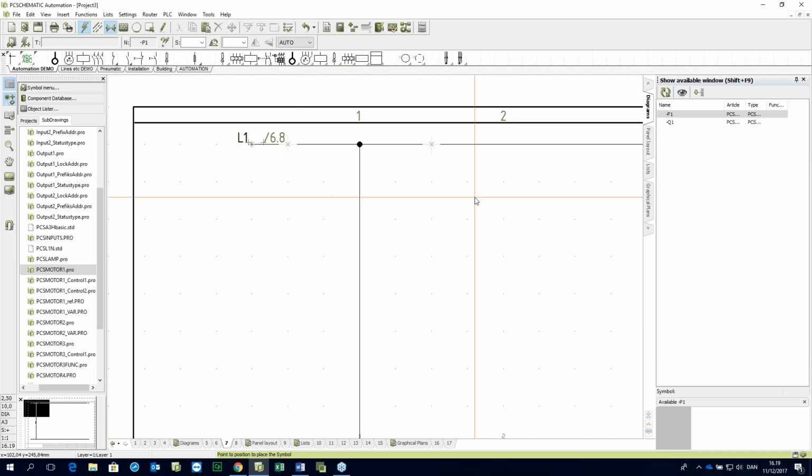The distance between my numbers here is 40 millimeters. And that distance is a recommended distance when you look in the standard that talks about technical drawings, or electrical technical drawings like this. 40 millimeters is the distance here. And if I want my drawing to be centered in the current path, then I'll have 20 millimeters on that side and 20 millimeters on that side, which again is 40 millimeters. And between those dots, I have 10 millimeters. So as long as you can see the dots, I think it's quite okay.